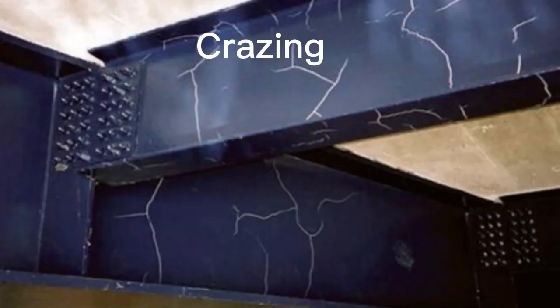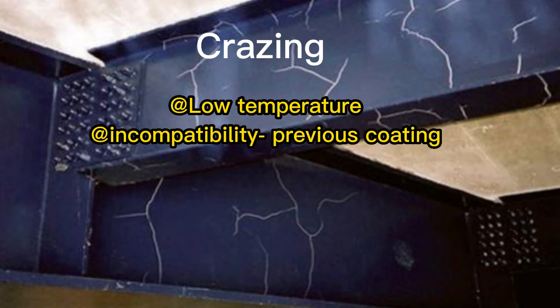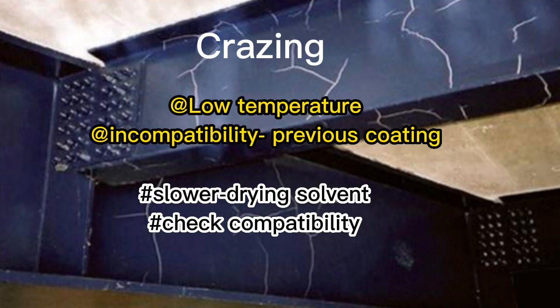Crazing is another type of paint defect, and it is caused by the application temperature being too low, incompatibility with the previous coating, or high film thickness. To prevent crazing, apply a thinner coat of paint and slower drying solvent. Check that application and drying conditions are correct for the paint system used, and check compatibility.